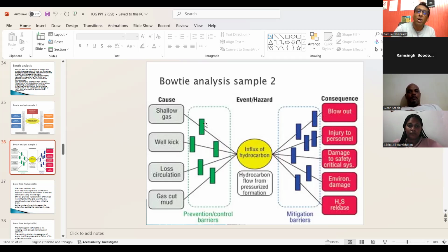And so the more of these you have, though, because you only have one here, but you can put more than one. The more barriers you have, the less likely that the fire would happen because of that cause, right? So if we said faulty electrical, a barrier here could have been regular inspection. Another barrier could have been purchasing good quality components, right? Another barrier could have been something called PAT testing. I don't know if you know this one. It probably wouldn't be known because it's something in the UK.